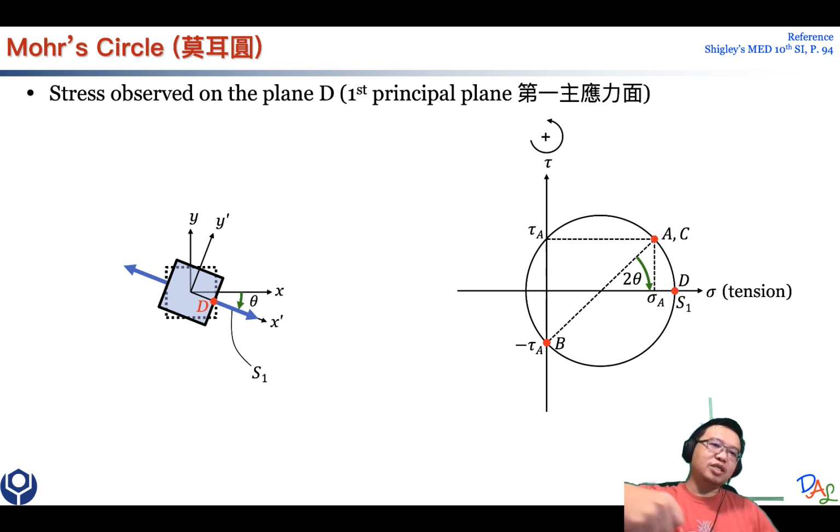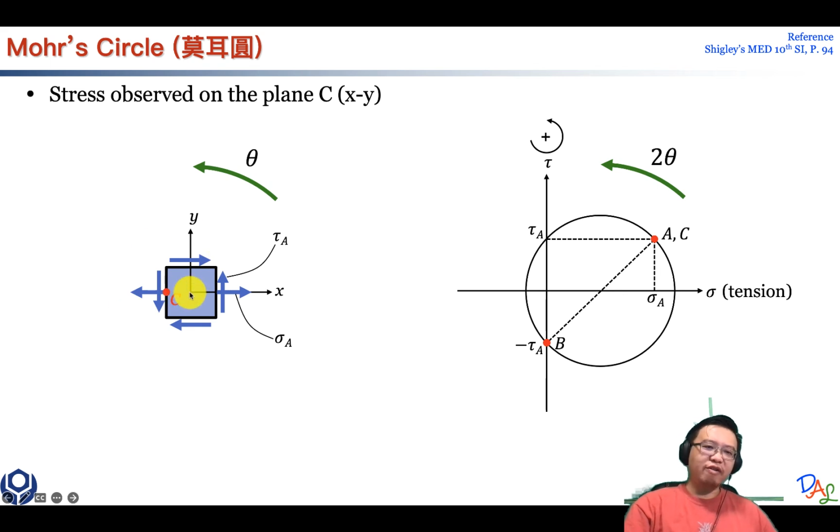So it's telling you that when this material is under this kind of loading, it in fact has the largest tensional stress along this direction. When we try to figure out whether this material could be broken, we should focus on the orientation where it's under the largest load, and we need to make sure whether along this direction, under this largest load, it is going to fail.